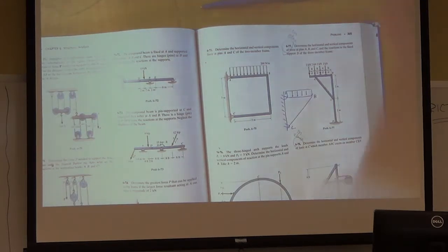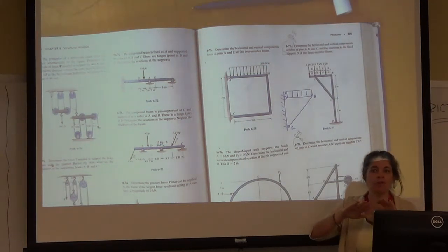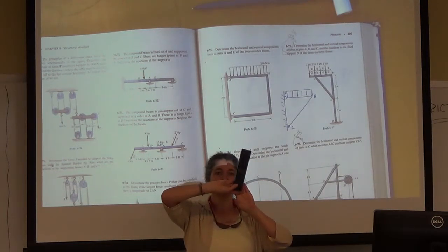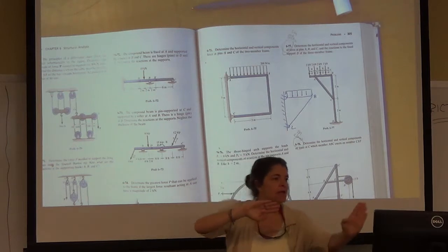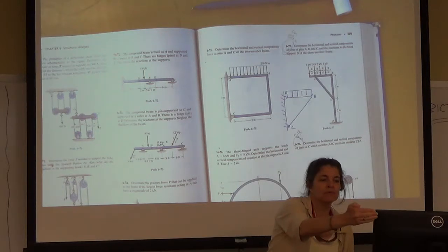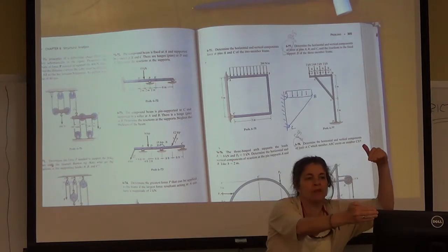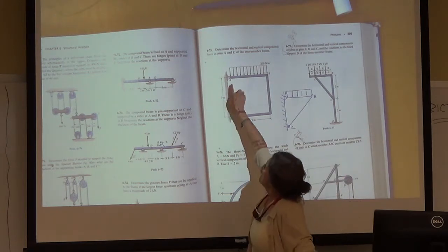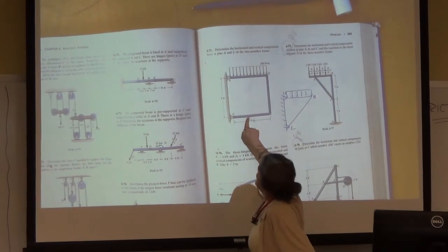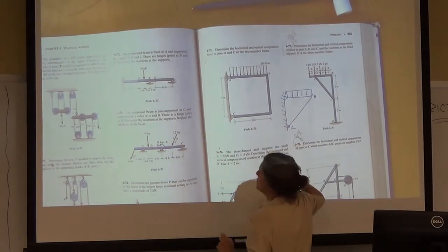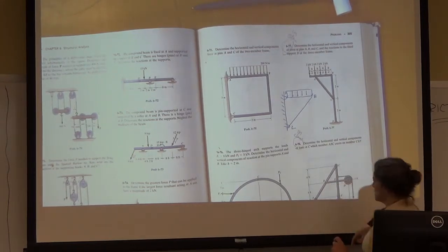No, that wouldn't be, because the only time we had an AX and introduced the prime is when there were 3 things coming together. Actually, 2 things and the connection to the wall. In that problem, here's the wall, and there was something here and something here. When you remove one thing, you have to account for it, and we had an AX and AY. Then when you remove the next one, you had an AX and AY prime. Here, there is only one member connecting to here. It's one disengaged member, so there's no prime. Same thing here.